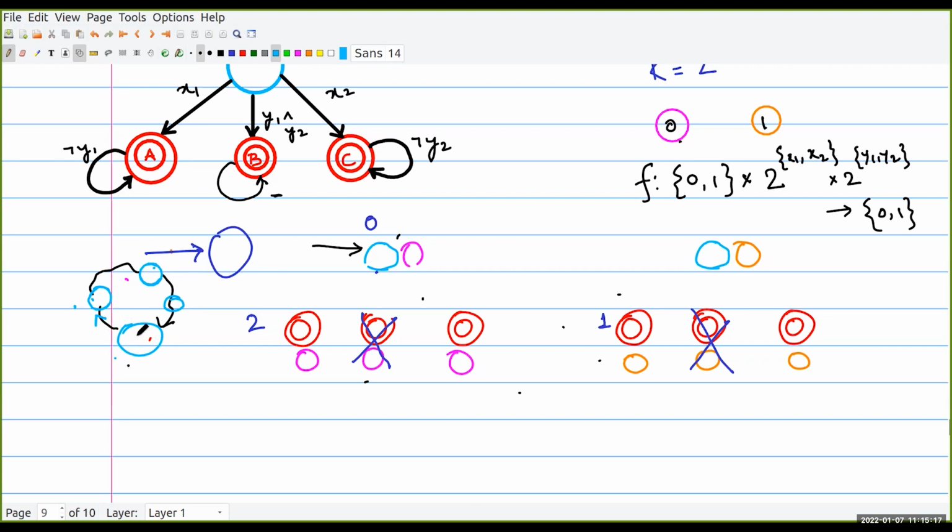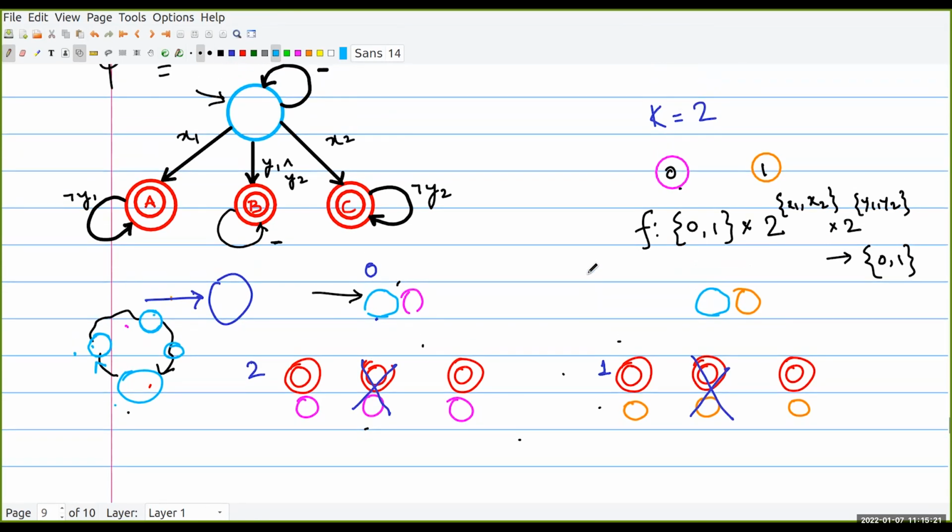Correct. Right. So, you do not know what your Mealy machine is. It may actually give rise to this. In the example we had, there was a cycle between these two. Now, unless I say that this can be greater than or equal to this and this can be greater than or equal to this, unless we put that equality part, we won't be able to satisfy this.